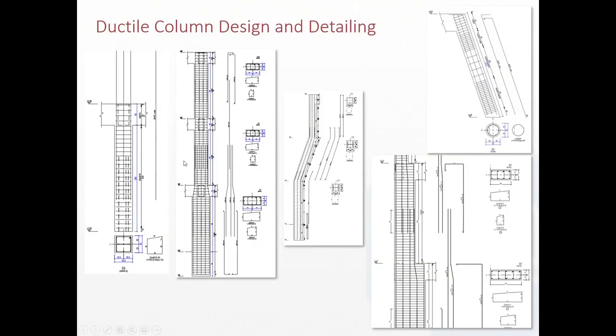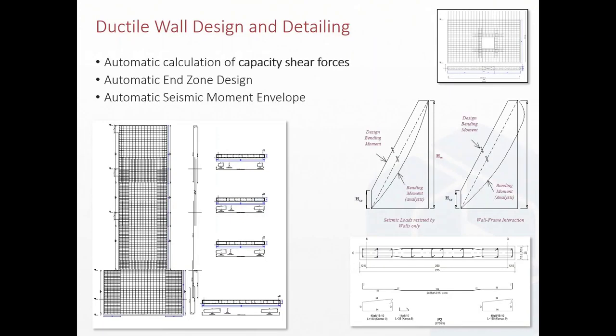Now the column design and detailing will all be done in accordance with the ductile detailing requirements. You can see different plastic hinge zones, and containment detailing in critical shear zones is being provided. When columns change in size and the like, the bars will adapt. If you've got bars that need to curtail because a column steps in too far, this is all automated. These are smart things that we're doing to help with the way in which the detailing has been done. Ductile design and detailing for walls includes the critical height zones, and designing the walls based on envelopes.